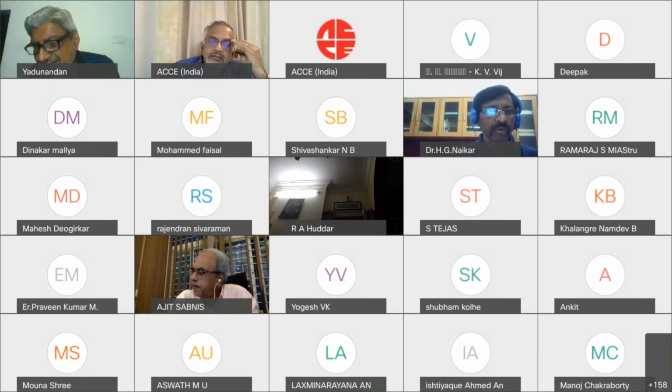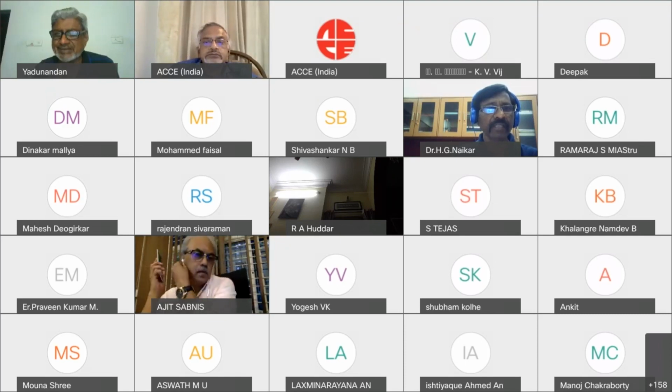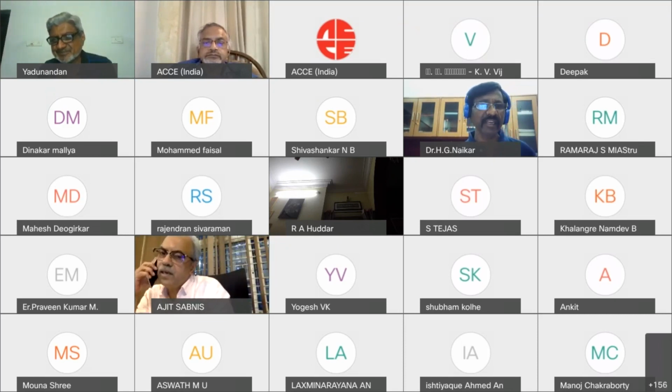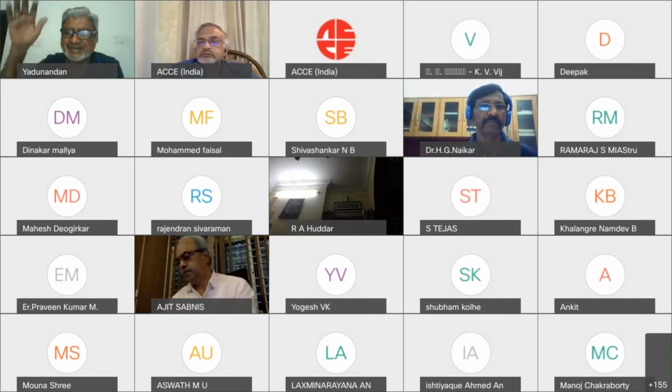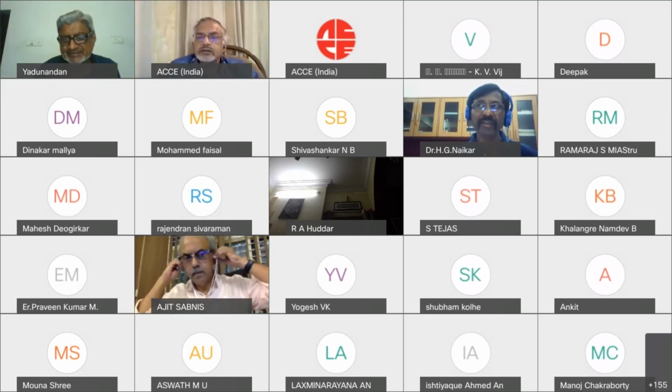Yeah, a two days gap is all right, sir. I don't think so. Maximum one day. Or immediate is the best thing. A two or three hour gap is good. Correct, but there will always be a tendency that outside people will delay a day. Our fundamental principle is that concrete will be cast within forms, and that is the best. Yeah, but obviously there is a difference between column and footing casting.